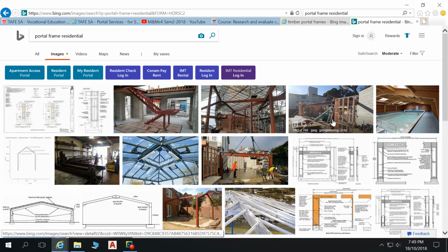So for a massive big window in here, because we'd need bracing in this wall, to do that bracing, we can just use a portal frame to brace it up. It provides that bracing, means we can have a massive window in there, or drive a car in there or whatever. Here once again, that scenario.